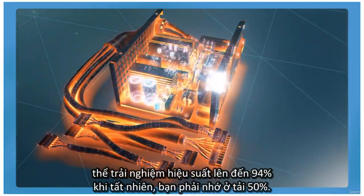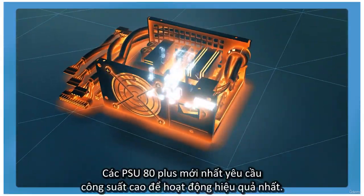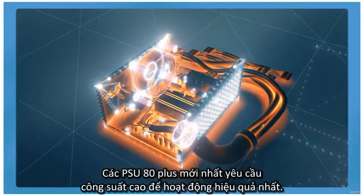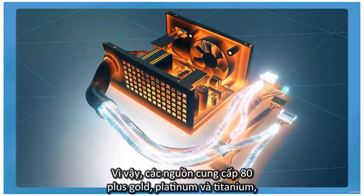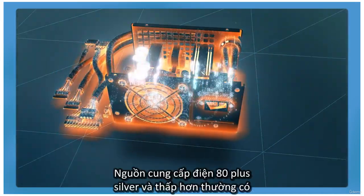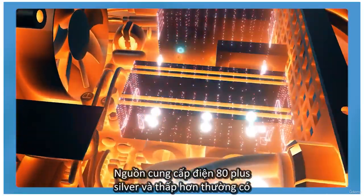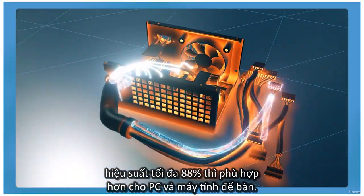When, of course, you have to remember, at 50% load. The latest 80+ PSUs require high wattage in order to run most effectively. And so the 80+ gold, platinum, and titanium supplies, up to 94%, are ideal for large data centers. 80+ silver power supplies and below, typically a maximum efficiency of 88%, are more suitable for PCs and desktops.